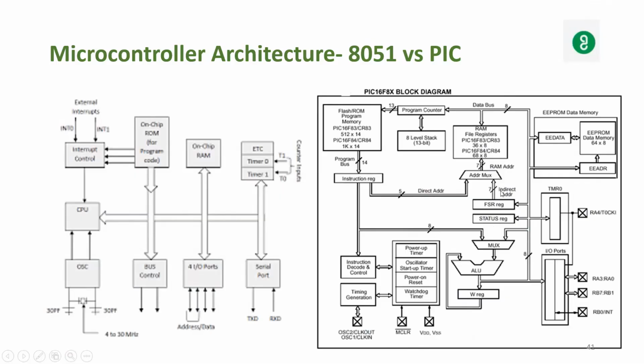And you have the file select register. It is an indirect address, and you have the direct address register. You have both direct address register and indirect address register. This is passed to another multiplexer. From this output, it is fed to the RAM memory. The next instruction that has to be fetched will be available in the program counter.